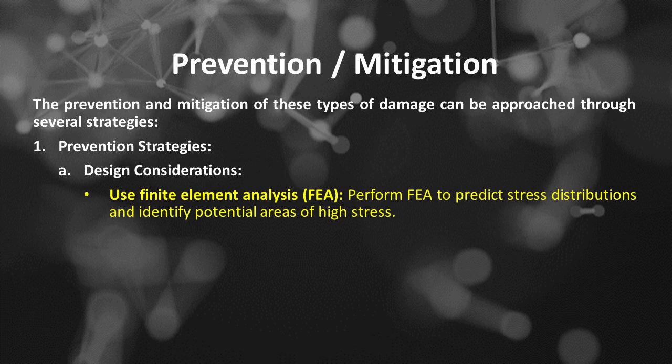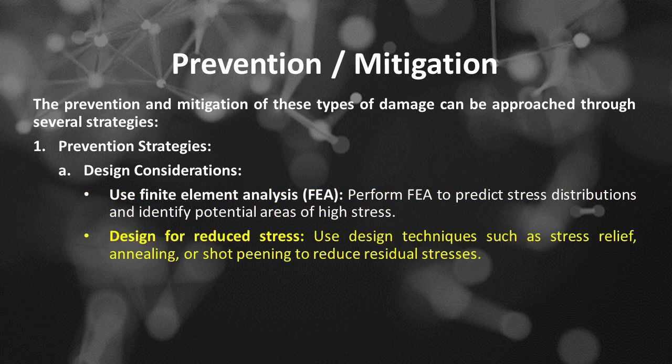Use finite element analysis, or FEA. Perform FEA to predict stress distributions and identify potential areas of high stress. Design for reduced stress. Use design techniques such as stress relief, annealing, or shot peening to reduce residual stresses.